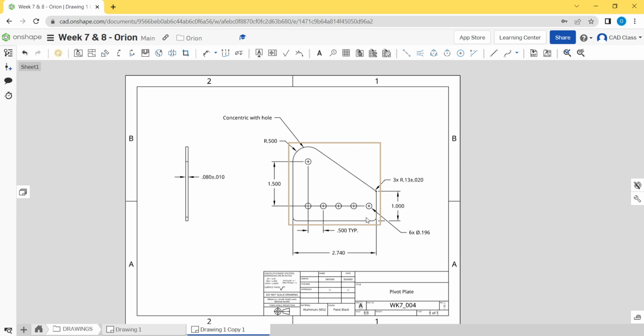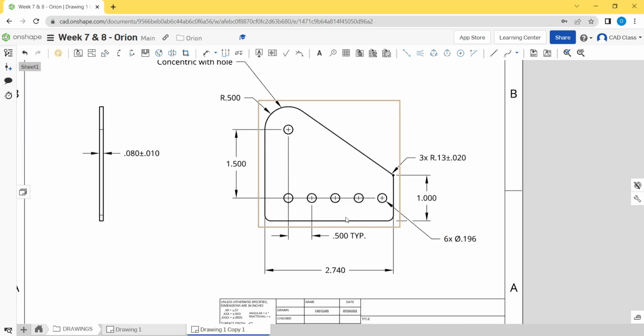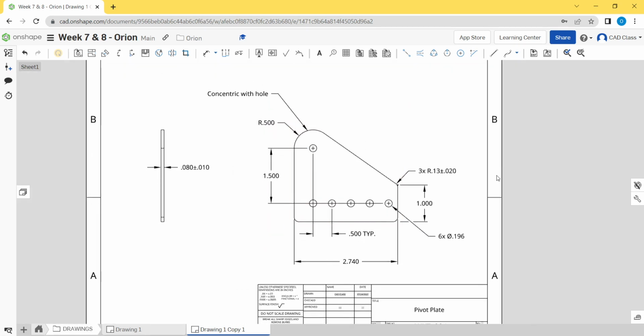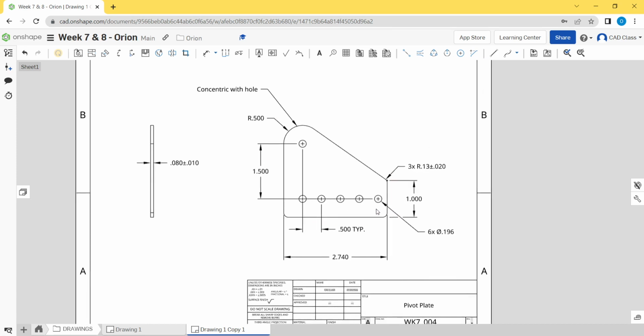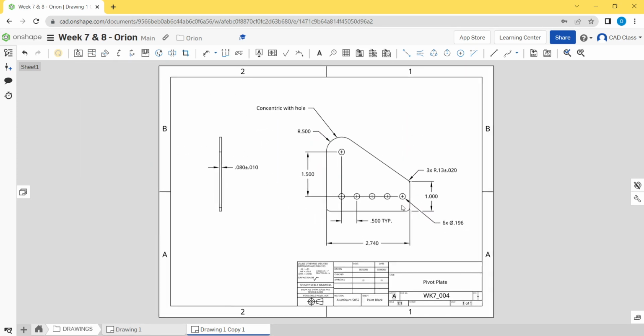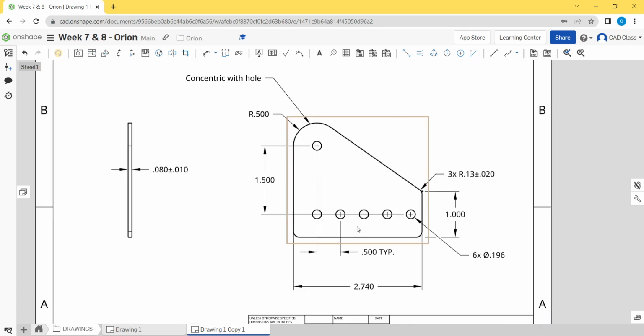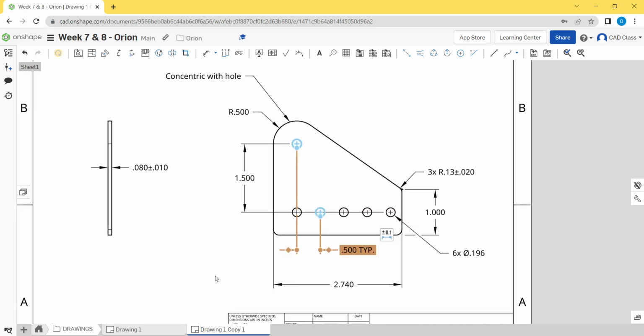Sometimes the solution is just to apply a tighter tolerance. However, the thing to understand is that whenever you apply a tighter tolerance, the manufacturing gets more expensive because it gets more difficult to hold that tolerance. I don't really want to go into it any more than that because it starts getting a little bit advanced for what we're talking about here. But just be wary when you're specifying spacings like this that are part of a long chain.